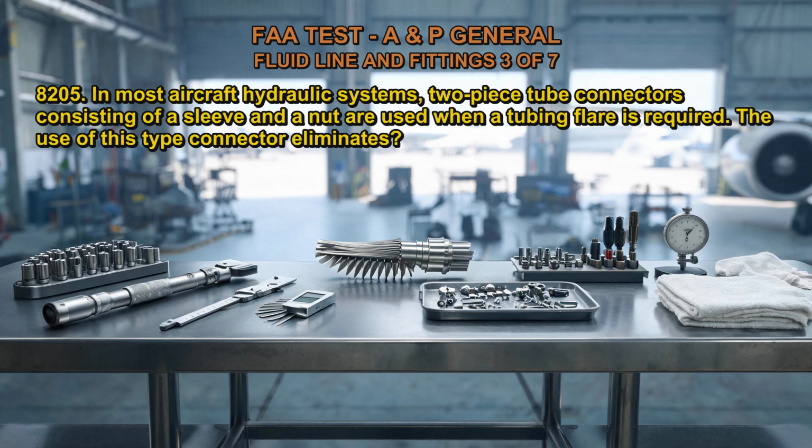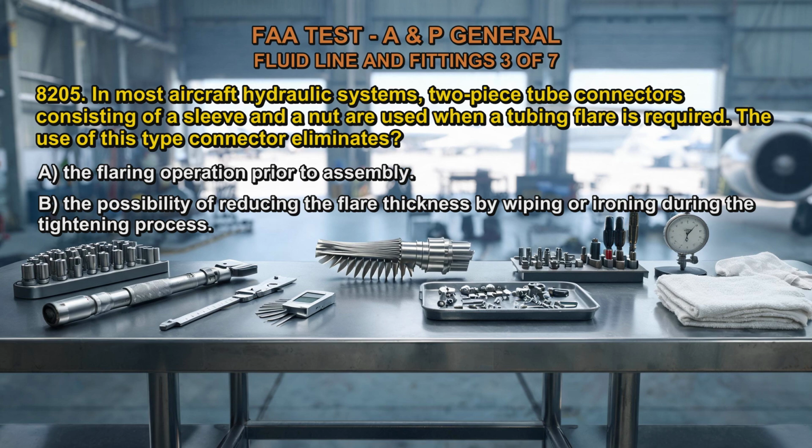8205. In most aircraft hydraulic systems, two-piece tube connectors consisting of a sleeve and a nut are used when a tubing flare is required. The use of this type connector eliminates A. The flaring operation prior to assembly. B. The possibility of reducing the flare thickness by wiping or ironing during the tightening process. C. Wrench damage to the tubing during the tightening process.